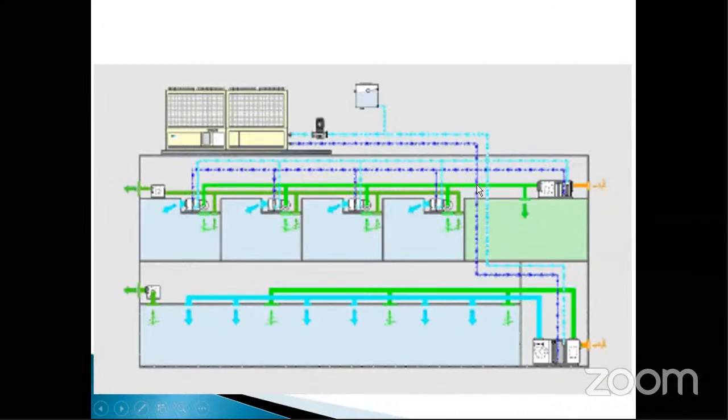So cool water, the temperature may be around 45 degree Fahrenheit, passes through the air handling unit, and the return line carries 55 degree Fahrenheit water, which goes down to the chiller. The chiller is a device which generates chilled water, and again the chilled water will be circulated to the unit and will return back. There is a duct which supplies cool air to the space, and we have a return air duct which takes return air from the space.